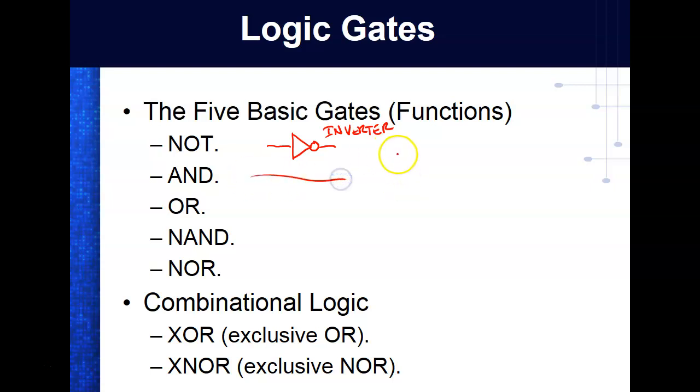The symbol for an AND is we draw the shape of a D, and then we put inputs. If I give these inputs names A, B, C and D, then A and B and C and D would have to be true or high before the output is. We call that an AND, and we're going to see how we can do this with contacts. If I wrote down the equation for this, I'd say A B C D, we don't have to put the AND. In algebra, if you put 2 expressions together, it means multiply, right?